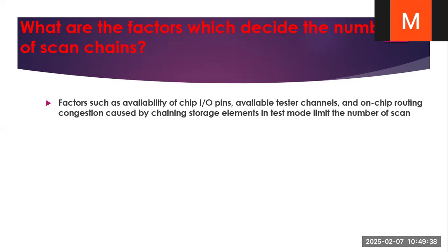Next question is, what are the factors which decide the number of scan chains? Factors such as availability of chip input pins, available tester channels, and on-chip routing congestion caused by changing the storage element in test mode limit the number of scan chains.